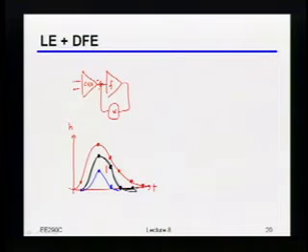Okay. So indeed, because you always have to throw away DC gain to get a certain amount of peaking, that means you'll actually get a larger signal swing by backing off like this. Okay? So when you really do combine these two things, that means that you really do want to set things based upon knowing how many DFE taps you're going to be using. You also want to build your linear equalizer keeping that in mind. Okay? And so I'll just mention this briefly.